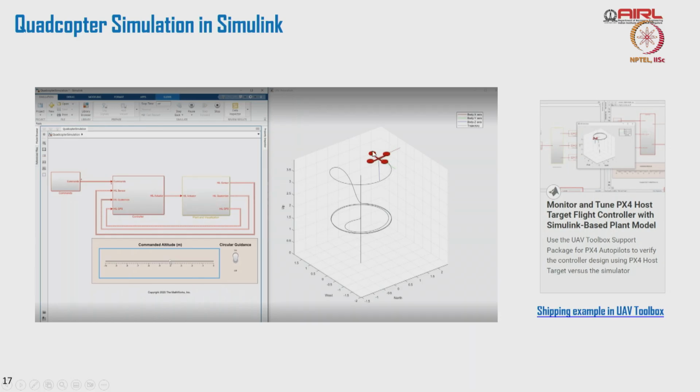These are the questions through which I want to understand the performance characteristics of it in a 3-dimensional plane, and how the drone responds, so I can assess quantitatively the tracking error and see whether the tracking error is acceptable for me or not. Basically, this validates your entire physical constraints present in the system, like actuator limits and everything, which can be verified to see whether you will be able to track the specific trajectory or not.